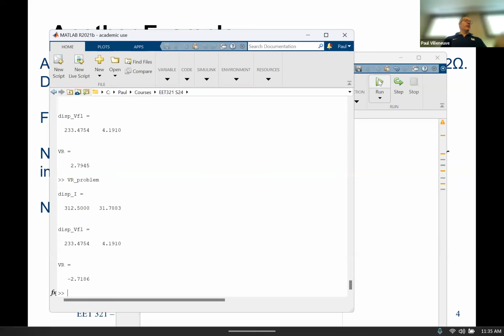Okay, so it's good that we didn't have it. That's a quiz, right? I made some mistakes. But yeah, so now what you see is the voltage drops when you go from full load to no load, the actual voltage is reduced. And that's because you have a leading power factor. So that reactive power that you get from the load actually helps boost your voltage. So when you have minus 2.7%, not that it's always positive, you can go negative though.